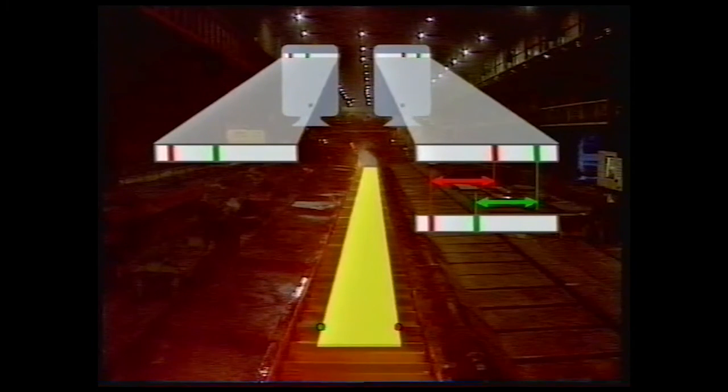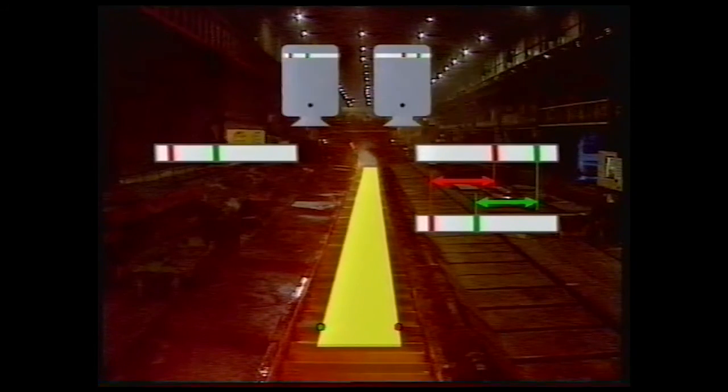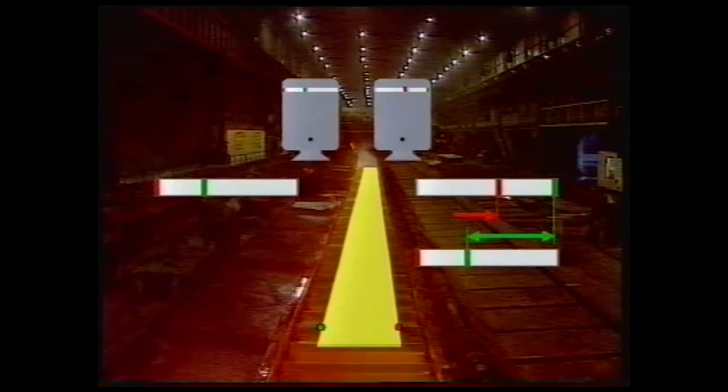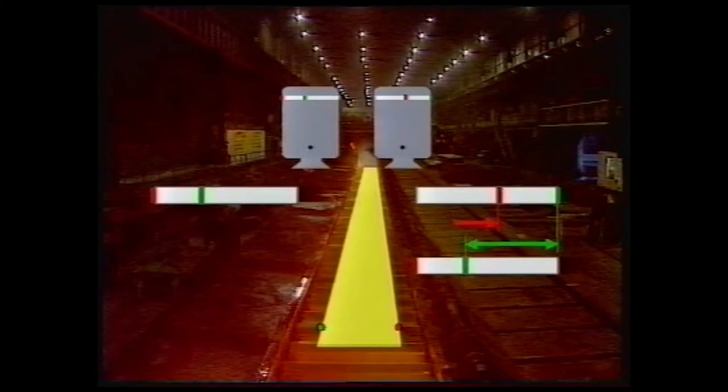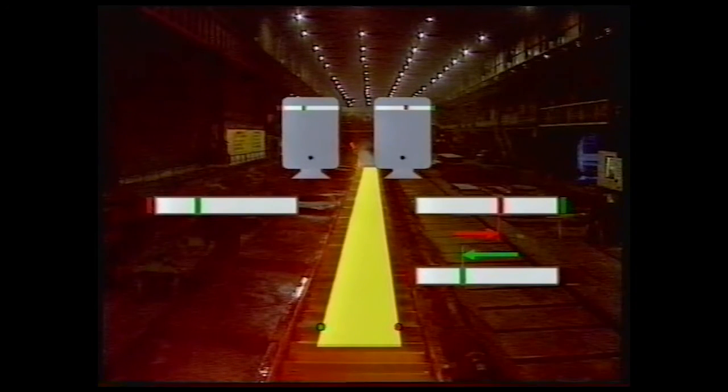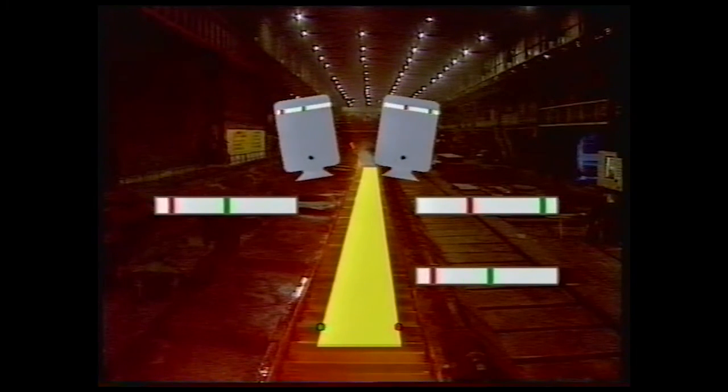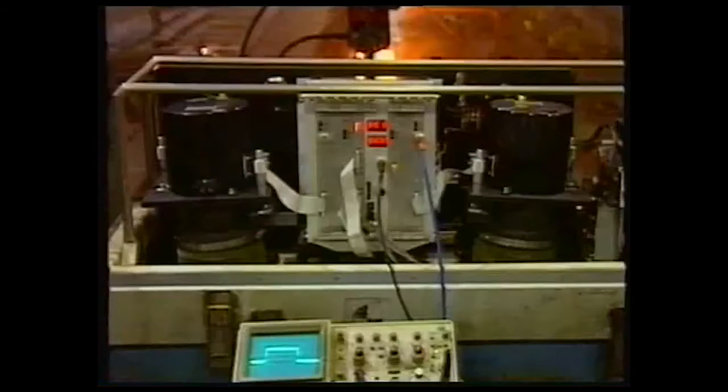In order to increase the accuracy of the measurements, one would like to make optimal use of the camera resolution. Bringing the cameras closer to the plate has its limitations because edges will soon fall outside the images. A good solution is to tilt the cameras, in which case they can be brought closer to the plate.